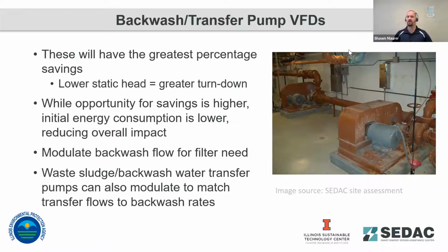Something else that was noted in the Q&A: multiple pump installations should have smart pumping programming controls. Looking at automation for plants and tying in VFDs to an automation system, especially where you've got multiple pumps that stage to meet different demand levels, is a good opportunity for VFDs and optimizing operation of pumps.